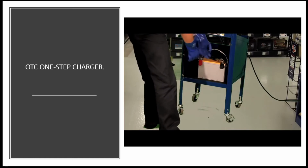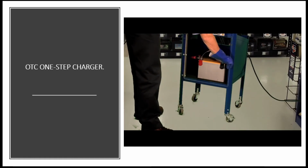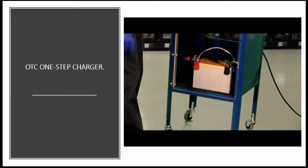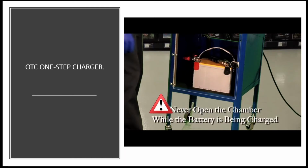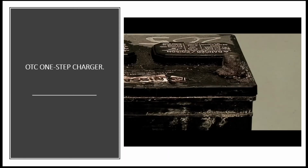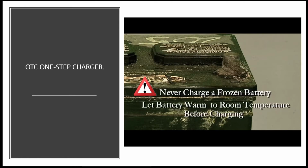Always charge the battery in the supplied charging chamber, with the door securely closed. The chamber is designed to contain debris and acid in the case of an explosion. Never open the chamber while the battery is being charged. Do not charge batteries that have physical defects, such as a damaged case or terminals. Do not charge a frozen battery. Since it can be hard to tell if a battery is frozen, let the battery warm up first if you have any doubts.